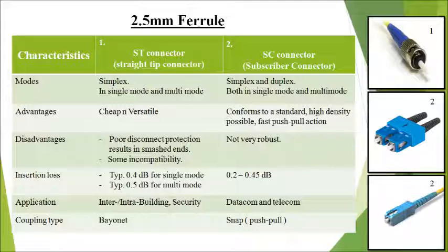The insertion loss of SC connector is 0.2 until 0.45 dB. SC connector have been widely used in datacom and telecom application. SC connector use coupling type of snap push-pull type.